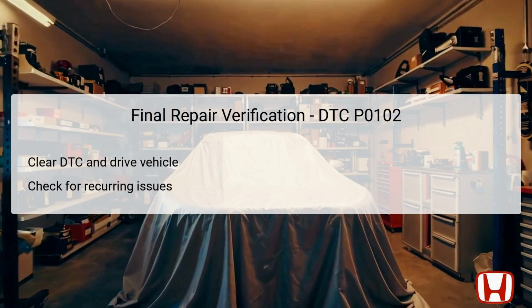Focus on evaluating the driving conditions that initially caused the DTC to set. Monitor engine performance, particularly during acceleration and idle, to identify if the check engine light reappears. If the DTC does not return after a few drive cycles under diverse conditions, it indicates that the repairs were effective, affirming the successful resolution of the issue. This final verification is crucial to confirm long-term reliability and functionality of the engine management system.